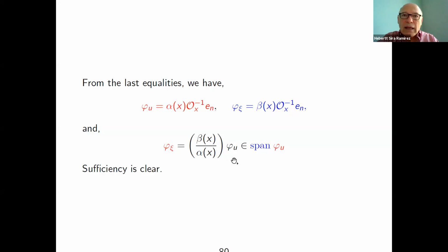And that condition of alignability between this input channel and this disturbance channel is necessary and sufficient for them to have the same relative degree. And therefore, a structural condition appears on the class of admissible disturbances that affect your system. They have to be in the same channel as the control input.